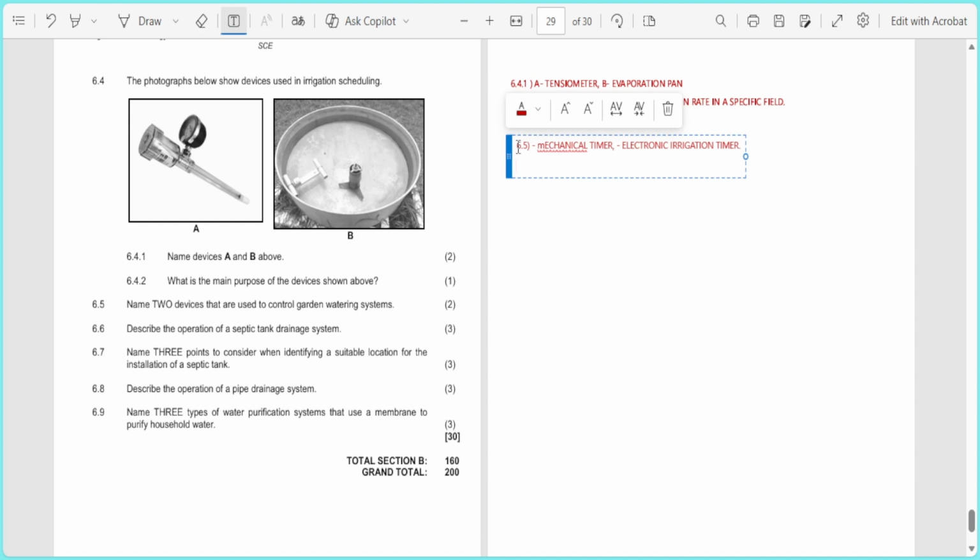The second tank allows further settling. By now the waste is mostly liquid. The stone trench provides a final filtration before water enters the soil. For critical maintenance, regular emptying of solids and never putting chemicals down the drain that kill the essential bacteria. That's the best description I can provide for this one.